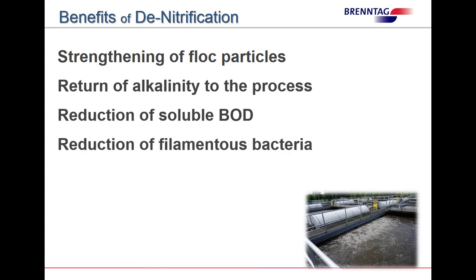Now, I get calls every year, usually about this time of year, on filamentous bacteria. That's the long bacteria that cause the foaming issues, the non-settling issues. And when you denitrify, most filaments don't like a 0 DO atmosphere, so you're just wearing them out. So it's a good way to get rid of some of them.